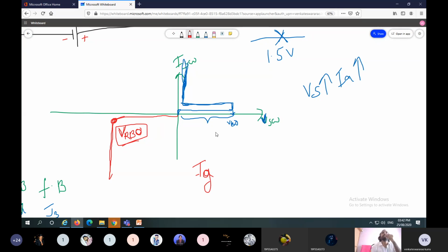This breakover voltage will be reduced by applying gate signal. If we apply gate signal at lower supply voltage, the thyristor turns on. So this one is new voltage due to applying gate signal IZ1. This one is new breakover voltage VB1.